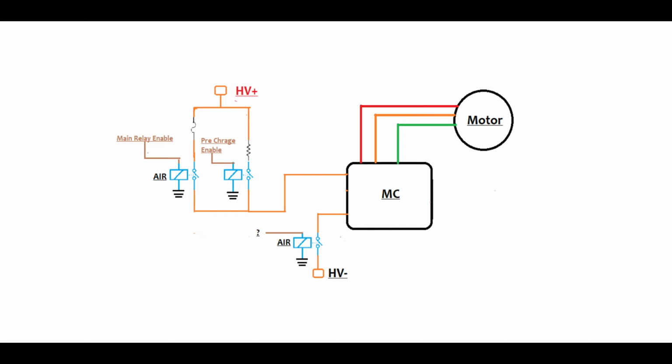Because beforehand, only having two relays, all we needed to do is engage the high side to either initiate the pre-charge, and then after the pre-charge, we can initiate that main AIR. But now it's like, what signal do we use for the negative side? Because the pre-charge and the main relay enable are going to need access to turn on this other relay.